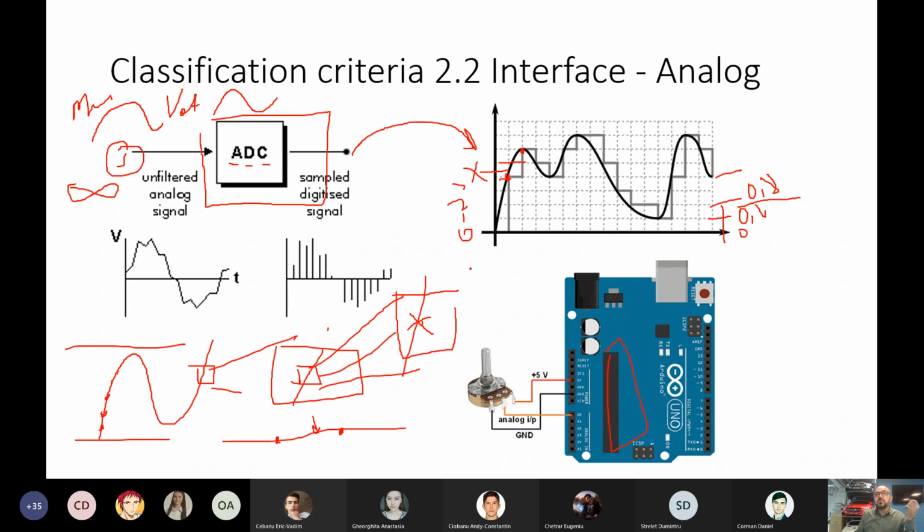why? Because we have zeros and ones. Okay, binary system. We cannot say that I have a binary on 8 bits and will have half of the bit. Never. So when we are digitalizing it, we are limiting the resolution according to the limit of the ADC. In this case, as in Arduino, we have 10-bit resolution.